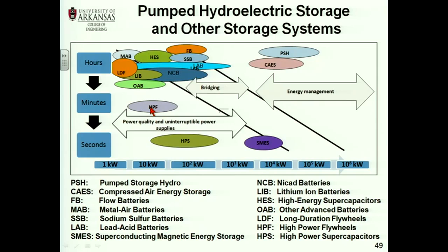It's velocity squared. So what are you going to do? Drop the speed to 1/2. Because once the speed drops to 1/2, what's happening? You have taken 75% of the energy. And it's not worthwhile to take the other 25% to bring it to a slow down.